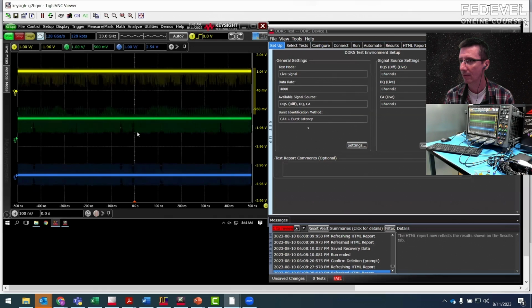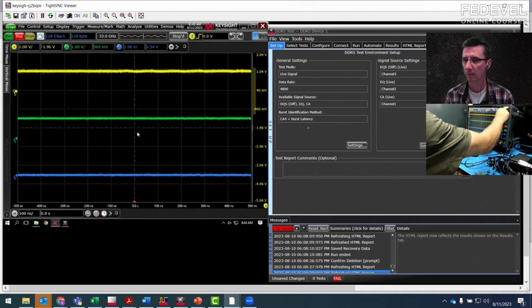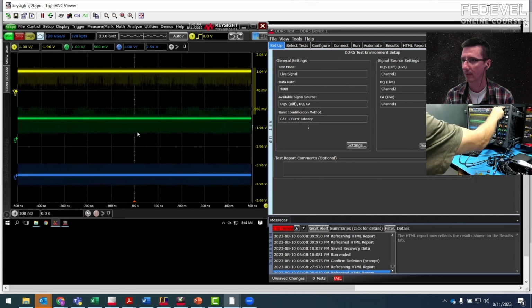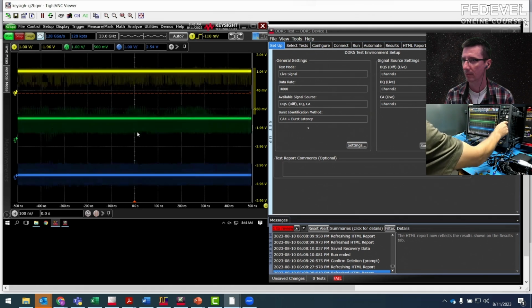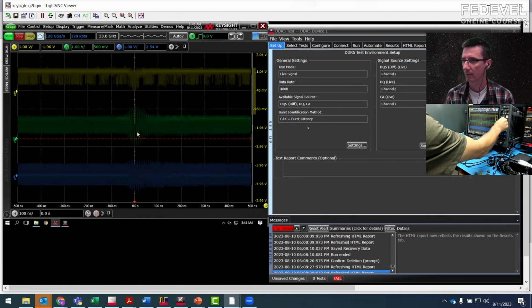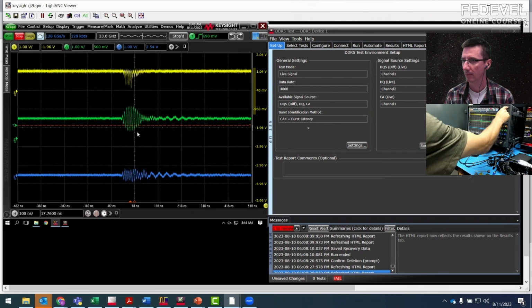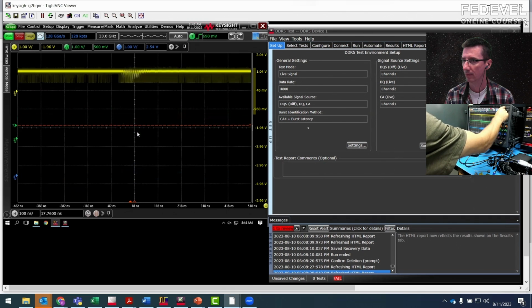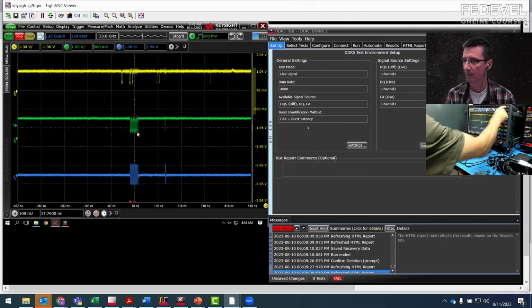Yeah, it's kind of going in and out, trying to get the right timing. I'm going to start. If we do just a single trigger, it looks like it's not very frequent, right? So the memory controller is definitely not fully active. In fact, if I set this to channel 2 and set the trigger down here, it's picking up this noise, but you get this very infrequent traffic.